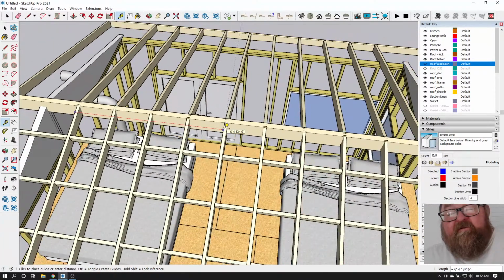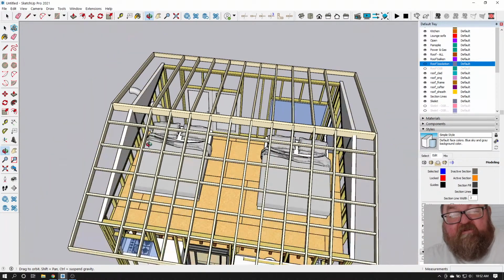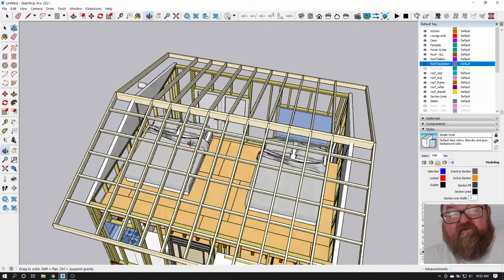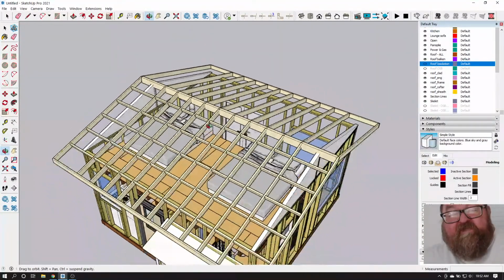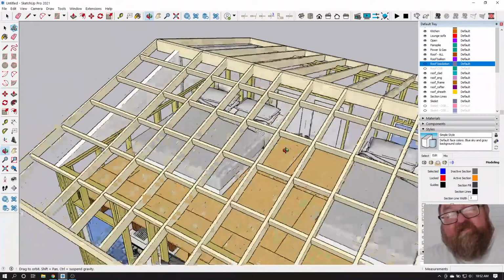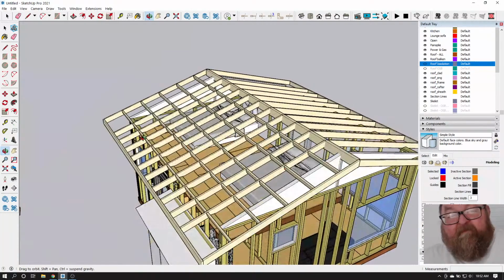So let's go down here, to the next one. You see? 1, 2, 3, 4, 5 is 8 feet. It doesn't work out on 4 feet, but it's okay because when you offset the joints on your OSB or whatever your decking is, it's just not perfectly in the middle, but it's still offset.